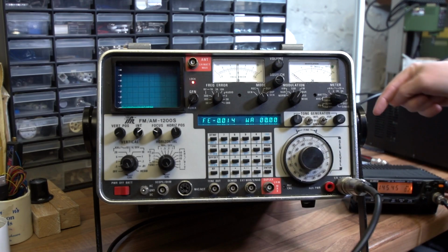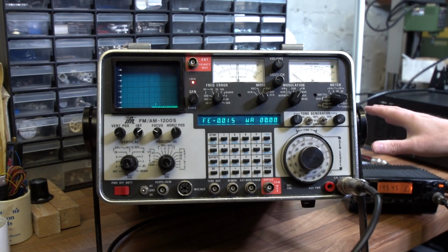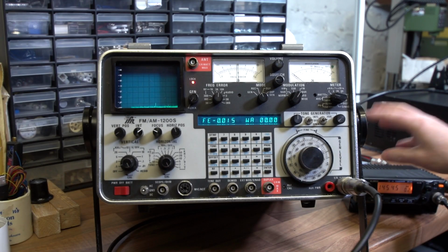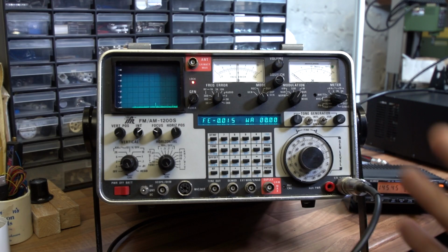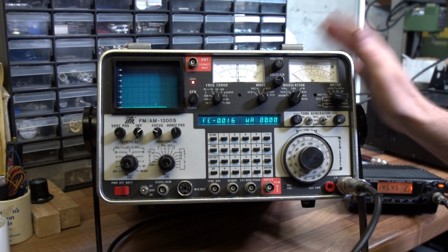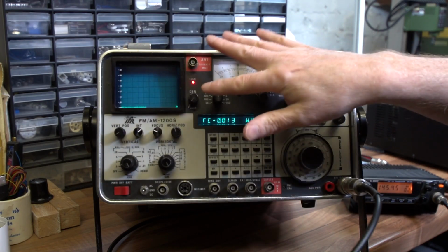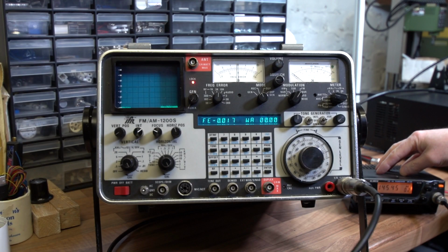It also does some clever stuff, like SINAD measurements, where you put audio from the output of the radio into it, and you can actually determine the noise level of the receiver and whether it's working to its optimum settings. Very good for setting up front ends and IF strips. So here's a practical application for the IFR 1200S, and like I say, this is quite an old machine now. These days you can get brand new machines with a digital display, but pretty much the same functionality. Right, so as I said, I've got the radio set here to 145.450.